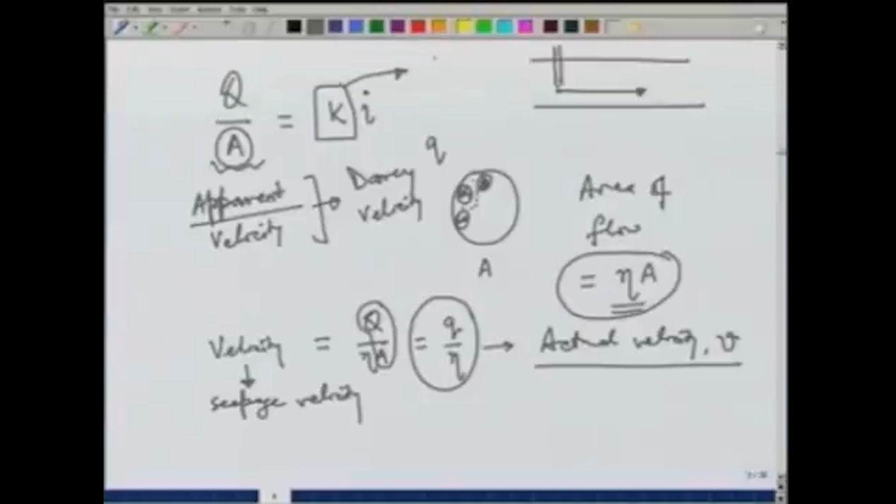Typically, gravel will have a very high conductivity, sand will have a little smaller, and clay will be very small. So, in order to have a formation which yields enough water and very fast, we should have a high porosity, specific yield and hydraulic conductivity.